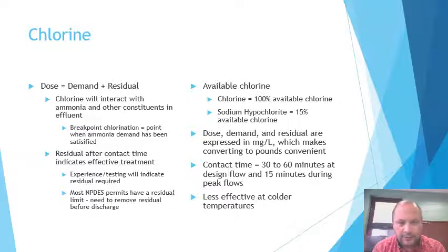So chlorine is very reactive, and all of those different reactions create what we call chlorine demand. So satisfying that demand, what you're left over with, if you've satisfied demand and you still have leftover chlorine, is called the residual.